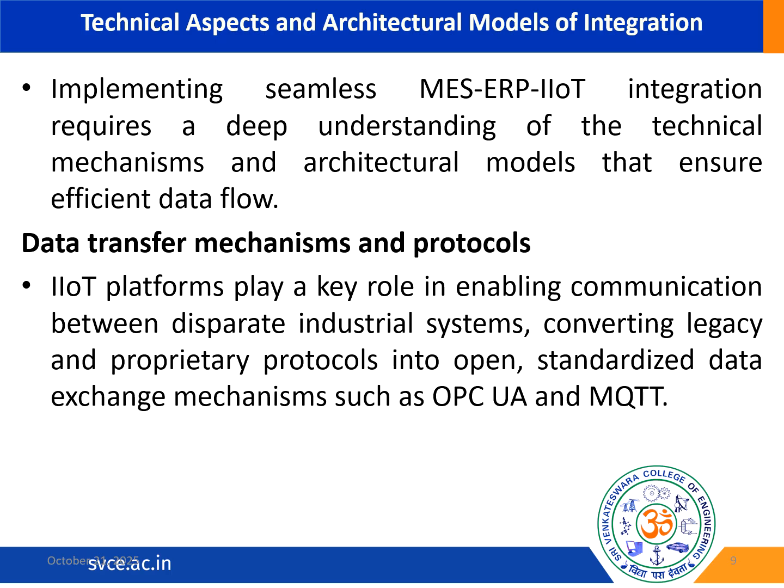So we'll be learning about the data transfer mechanisms. This enables the communication between industrial systems. We should have a deeper understanding of all these protocols. When you consider the OPC UA protocol, it is widely used for vertically integrating the machines with MES, ERP, and SCADA systems. This protocol ensures secure and reliable data transfer in an industrial environment.